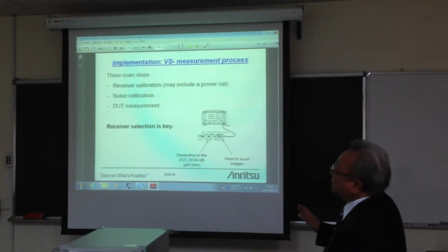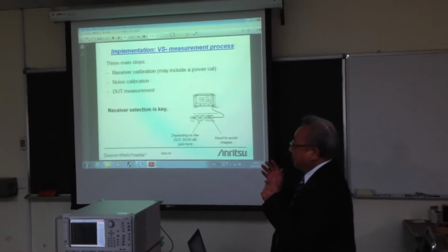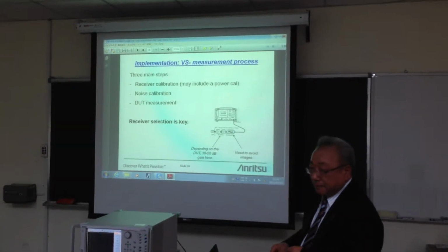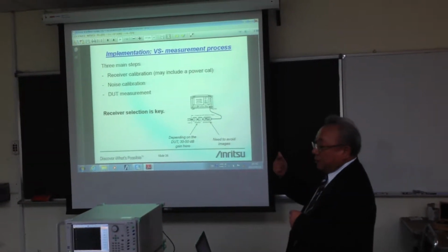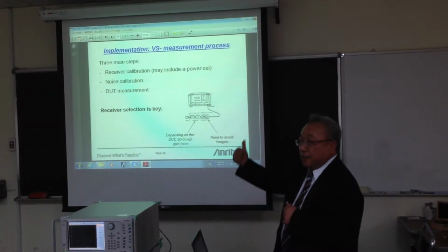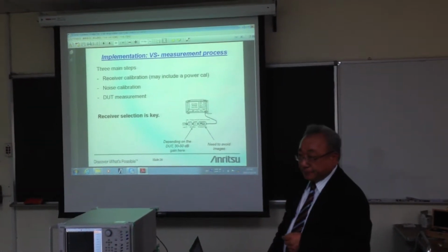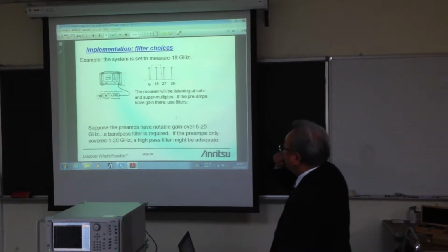For the noise figure measurement, first I have to measure the DUT S-parameters. Then I load that S-parameter data to the VNA, and it calculates the noise figure.